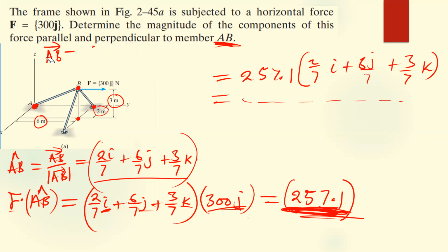So at B there, you're going to have something like this. And then we're trying to find the unit vector of this one. We have found it, the unit vector of this line. If you find the dot product of this same line with this force here, it means that you have found the value of this force along this same line.